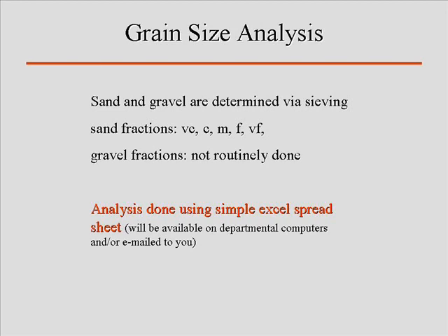But the hydrometer method always bothered me because every 5 minutes you're going back and taking another reading, and frankly, I don't want to come in at 3 o'clock in the morning, damn building's locked. You know, I just don't like it. But you don't have to do all that pre-weighing stuff. And the hydrometer method gives you those data that you need for doing the statistical analyses because it allows you to come up with a curve. This gives you physical samples.